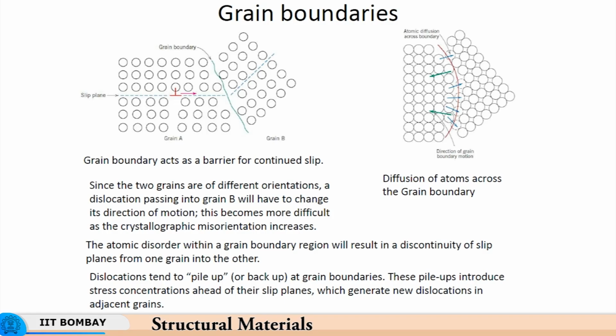So initially the grain boundary is strong, and as temperature increases progressively, the grain boundary becomes equal in strength with that of the grain, and then its strength reduces below the strength of the grain. So the temperature at which the two strengths are equal, so grain boundary is as strong as the grain, is called the equicohesive temperature. So, below the equicohesive temperature, the grain is weaker, the grain boundary is stronger. So, grain is weaker means the grain deforms, grain boundary does not deform.